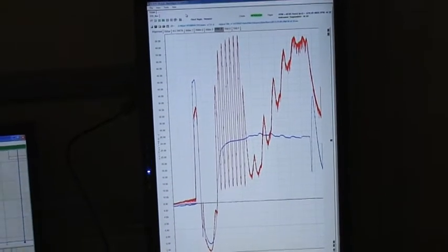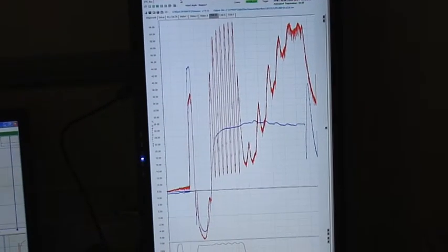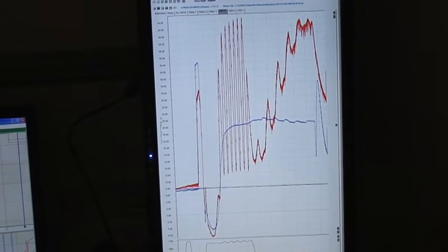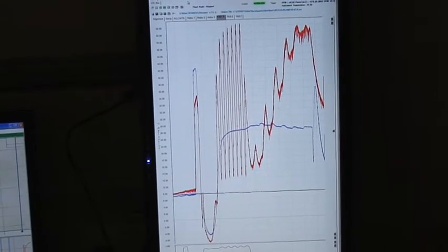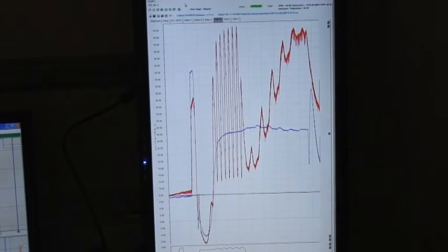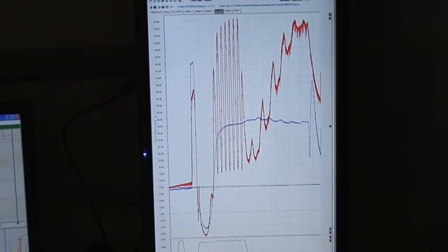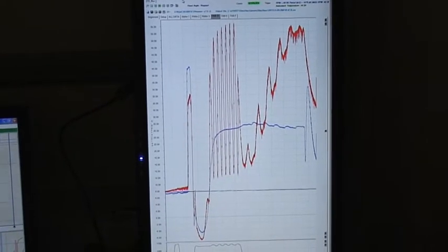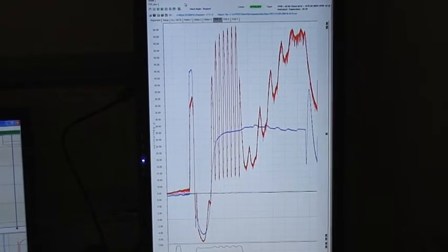The blue trace is using a blue laser which is absorbing at these temperatures, and that shows a roughness measure of the wafer as we grow the initial gallium nitride on the sapphire, as the material has to smooth out slowly during the initial growth to remove the dislocations.